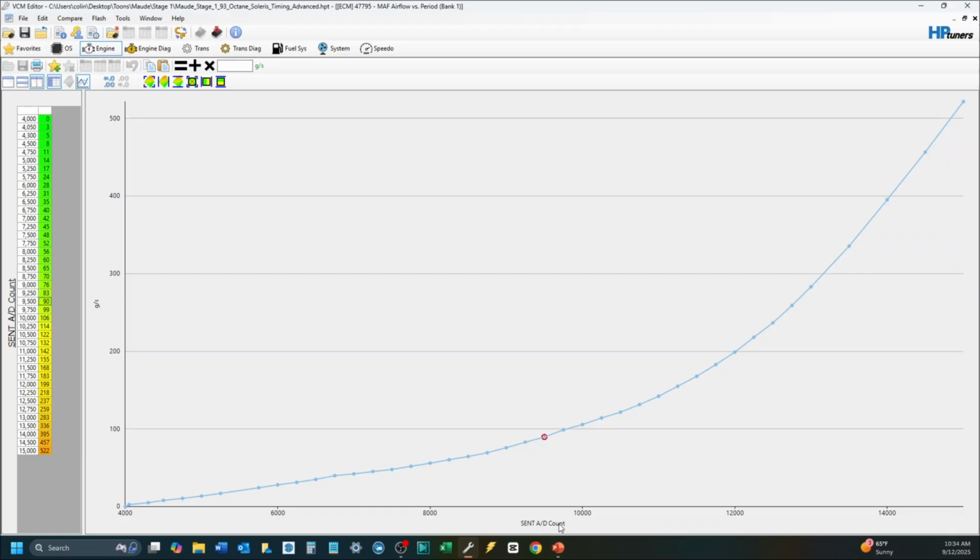Oh, well, I won't try and remember here, but AD is the analog to digital, right? Something, the nibble transmission protocol, right? You don't need to know all that. Just understand that it's a little device sitting on the voltage sensor, and it's sending out pings that essentially correspond to voltage. These values here from 4,000 to 15,000 are basically voltage, right? And I could add a modifying function that would make it just voltage, right? But it's a little half-baked.